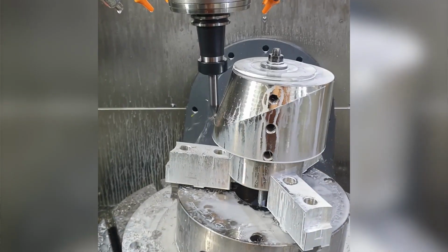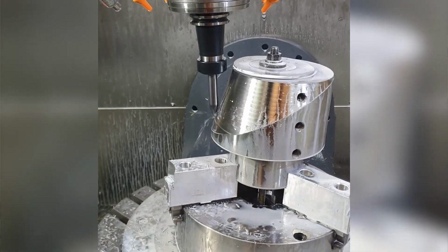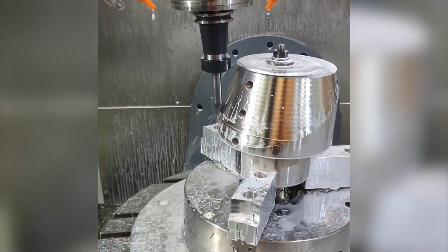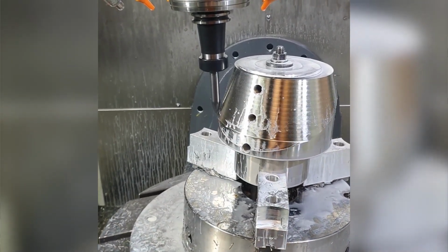Thanks Lars for the detailed explanation of the key capabilities of the new Wall Finish Barrel Swarf operation. I just wanted to emphasize that this innovative 5-axis operation expands the industry-leading multi-axis machining capabilities of NXCam. Additionally, I would like to highlight some of the remarkable benefits you can achieve with this cutting method. In this machining example, we used a 3/4 inch barrel cutter to machine a conical surface with a zig tool path and simultaneous 5-axis non-cutting moves.